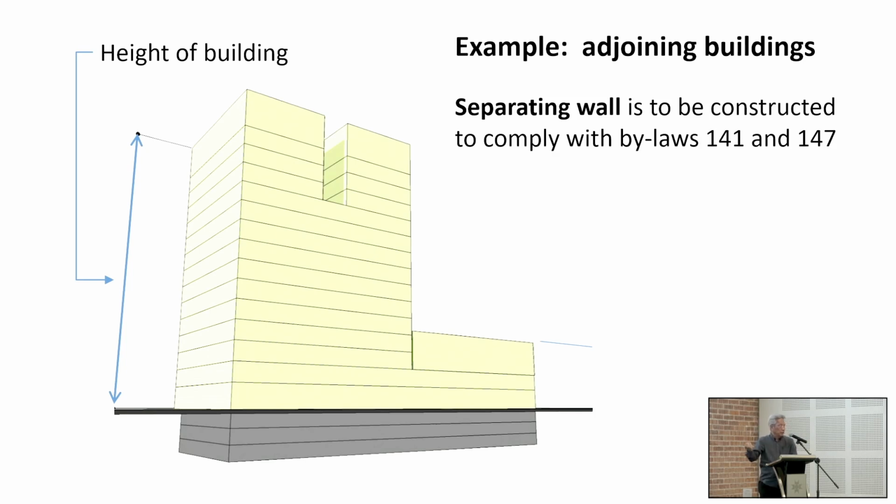So, for example, for fire lifts, you need a coverage of 60 meters. In this situation, the riser coverage is 45 meters. So you need fire lift coverage of 60 meters, and the riser itself is 45 meters only. If I have a building like this, and this is one single building, I put the fireman's lift and the risers at this corner. I may find that I will not be able to cover this area. So I'll need a secondary riser on that side to cover this building, right? Because this is one whole building.